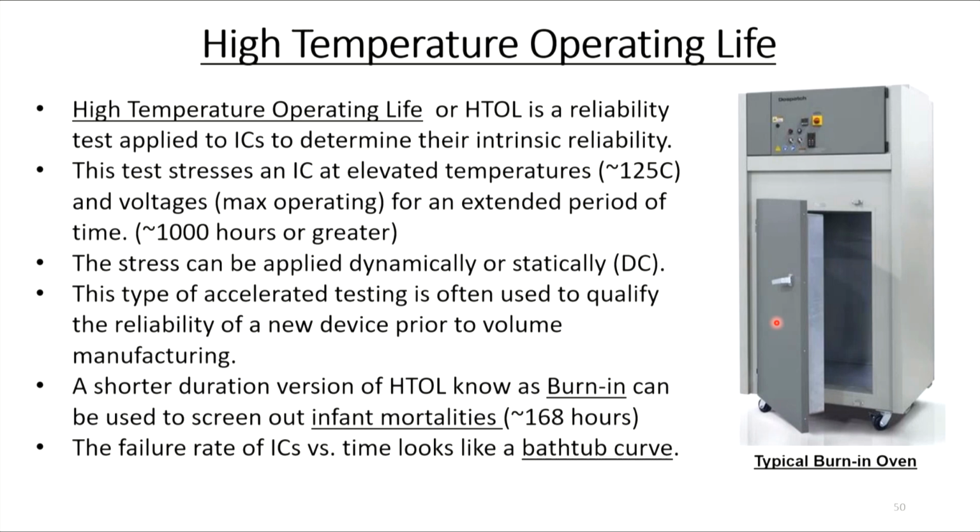Switching gears yet again. I'm going to talk about high temperature operating life now, and that stands for HTOL. And this is a reliability test applied to ICs to determine their intrinsic reliability. It stresses the IC at elevated temperatures and their max operating voltages for extended periods of time, maybe 1,000 hours, 2,000, 3,000. And this stress can either be applied dynamically, switching, or statically, DC. This type of accelerated testing is often used to qualify the reliability of a new device prior to volume manufacturing.